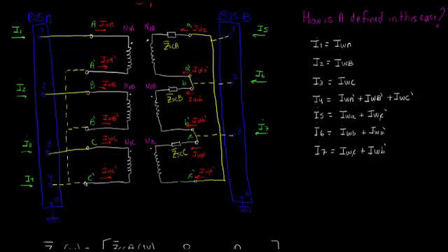Finally, we can also verify the addition of the no-load losses and the magnetizing current for this case. Remember that both of them are added in the secondary of each single-phase transformer. Then, in this case, we have an impedance ZOC between nodes A and A', B and B', and between nodes C and C', all lowercase.